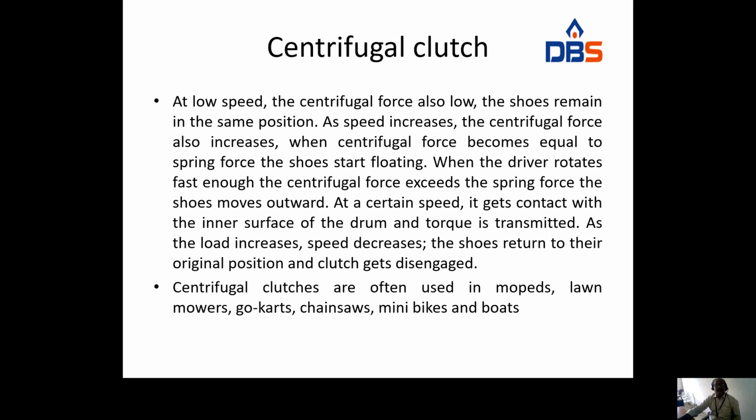Centrifugal clutches are often used in mopeds, lawn mowers, go-karts, chainsaws, mini bikes, and boats. There is no clutch pedal. If you increase the speed, automatically the clutch transmits more amount of power. So this is the mechanism in case of a centrifugal clutch.